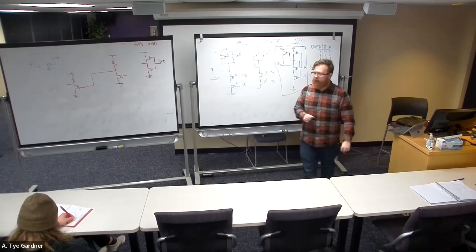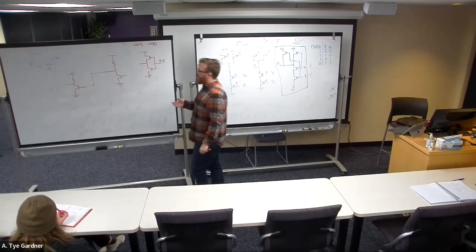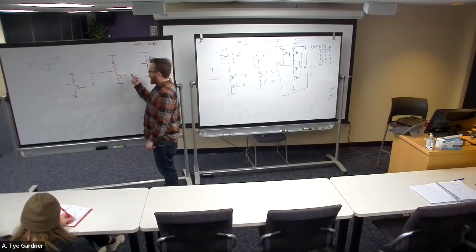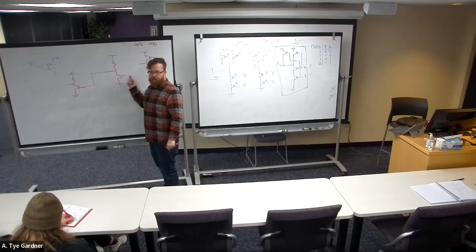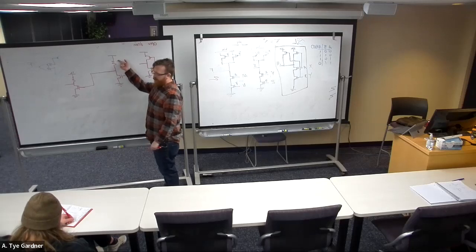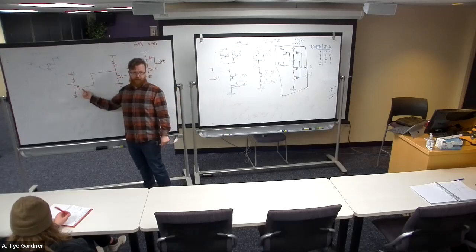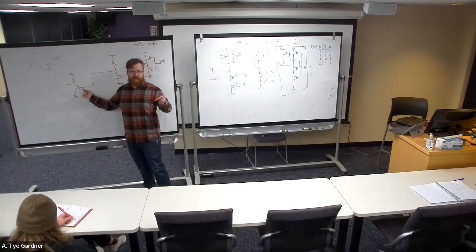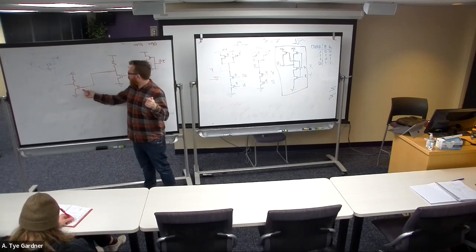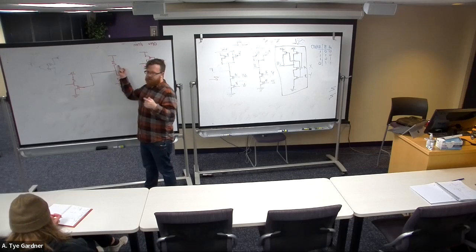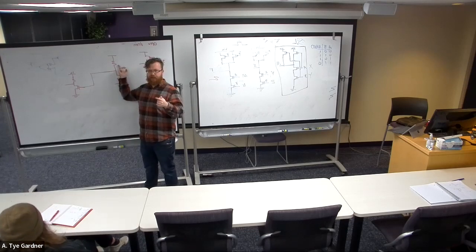Now what happens? Well, this inverter, if it turns a 0, then this resistor pulls it up, right? So I get a 1 here. That 1 here is plugged into a gate. And as I said, gates have 0 input current, right? There's no current, which means no current is flowing through this resistor.